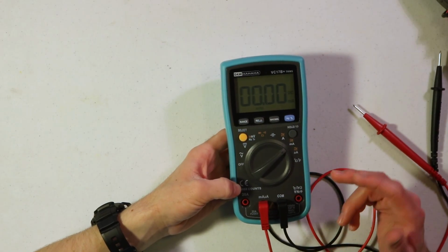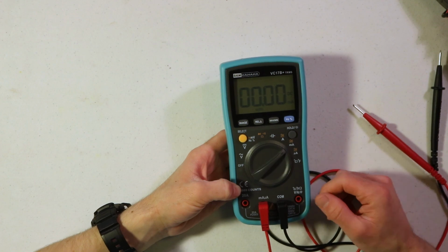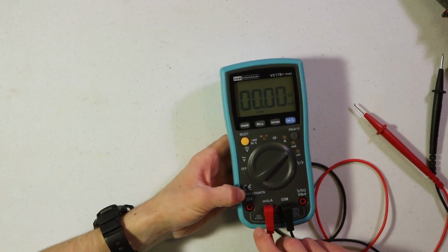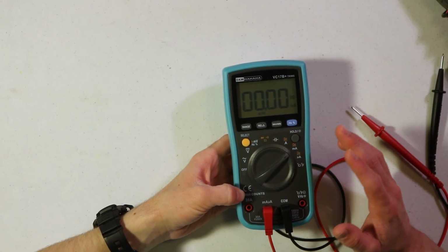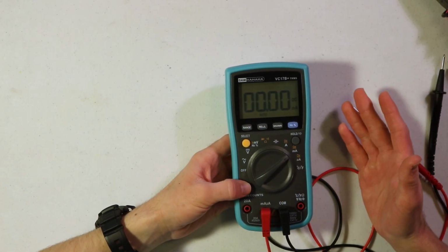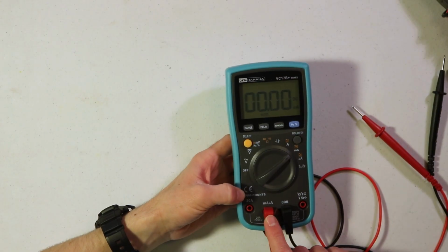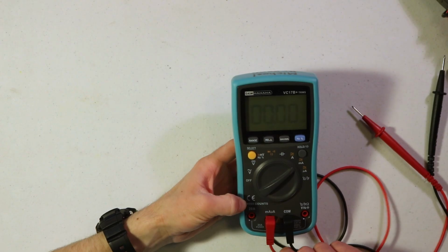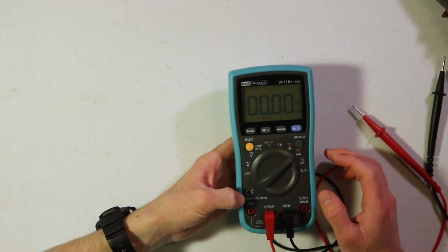And I did that with this multimeter. I don't know when. It just doesn't work now. So if I leave it here on the lower current rating and I try to measure current, I don't get any value from that. So please keep that in mind. If you don't want to destroy your multimeter and not be able to do the labs, then make sure that you always connect it in series and connect it on the right port depending on the range of values that you're going to be using, so that you don't burn out your fuse or destroy your multimeter and make it no longer usable.